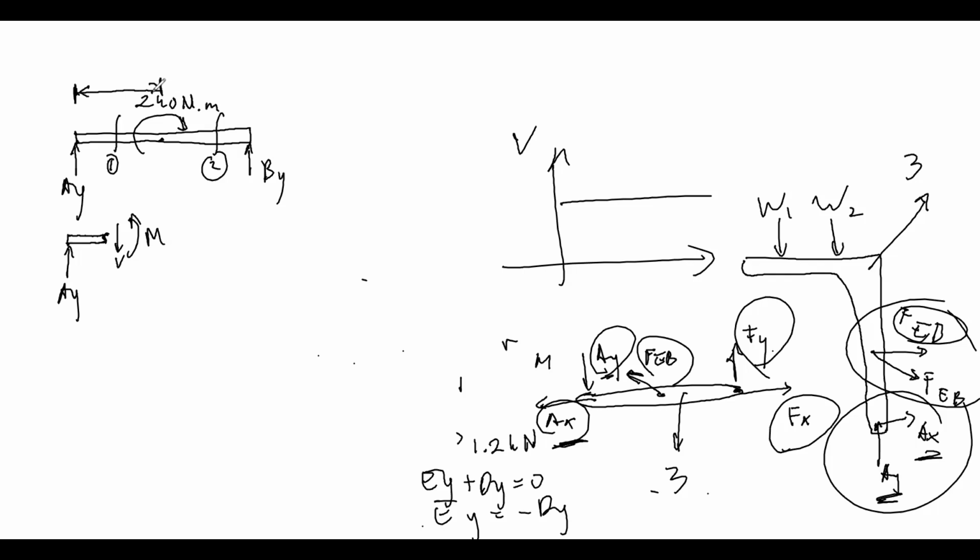If the cutting happens in between those two, you don't have to include the moment, right? So your free body diagram will be like this. But remember, you have to draw the distance there with x instead of the actual value.